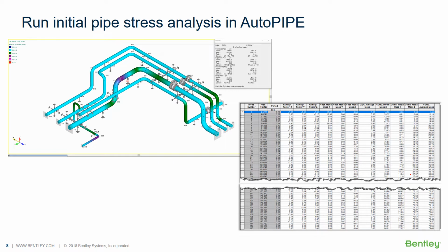We have our code stress plot on the upper left, which is showing that our highest stress is occurring at point C11 in the expansion case. And if we look into the dialog box, which shows a little bit more detail about what's occurring at that point in the different load cases, we would see that the highest ratio is 0.68 at C11.